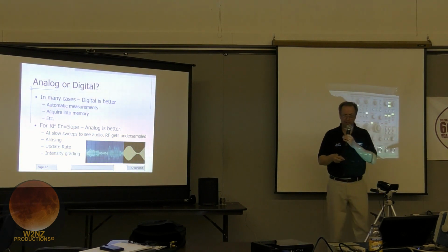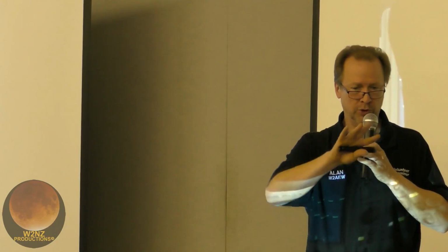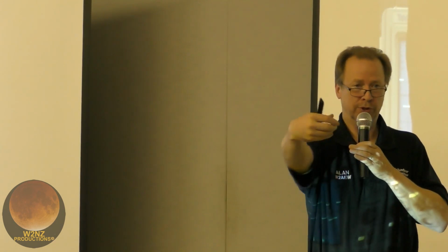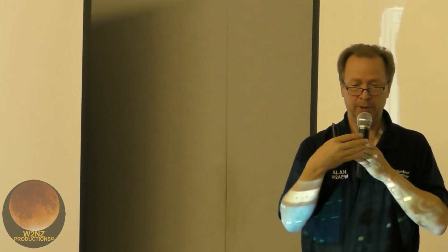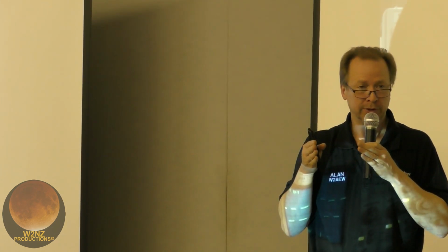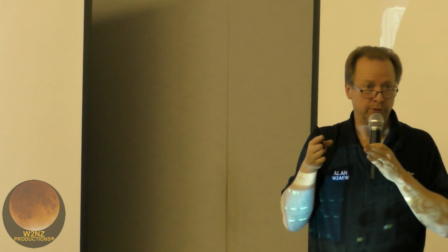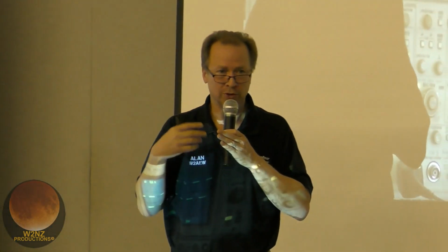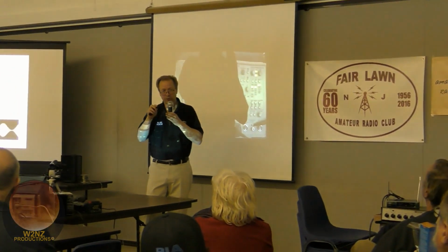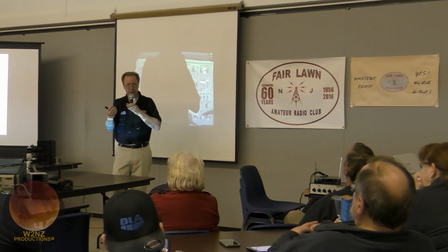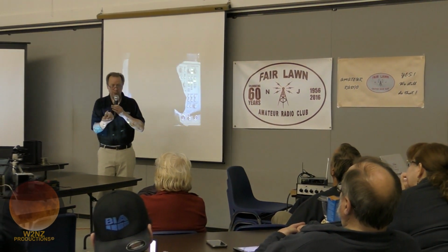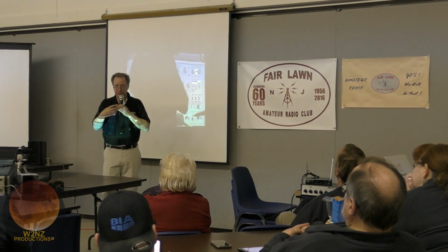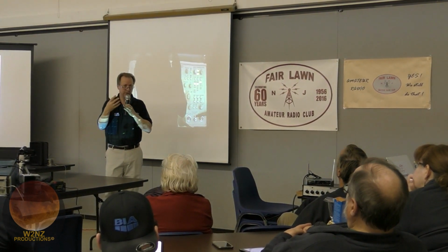But the bottom line is the waveforms that are used to stack on top of each other and build that color bitmap are a given length or a given horizontal time base. So the sample rate is still going to be driven by that. So you still have the potential of aliasing, unless you turn the memory up. You turn the memory up, then things get a little sluggish because there's a lot more memory that the thing's dealing with. So even though you do sometimes have this color grading, you'll still have that downside of not properly sampling the signal, or if you are, getting a sluggish enough response that it isn't really giving a live update.